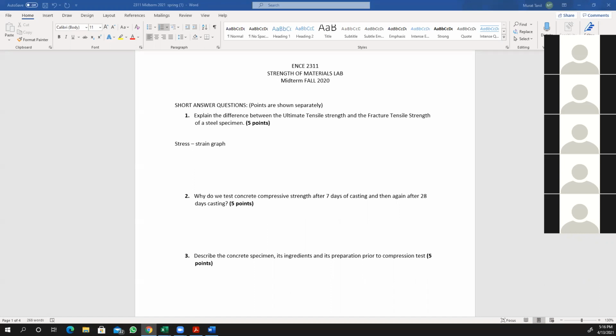Let's say you are working on highway construction. There is a bridge that is damaged, and you are going to pour concrete, and your job is to open the traffic overnight, because at nighttime the traffic is low, and the daytime traffic is much more heavy. If you see that type of problem, what you do is order the concrete with specific admixtures added into it. That gives you the 28-day strength overnight or in 2 days. There is no spec. It depends on the mixture. I can't give you exact numbers, but I can pull up Google right now, and it will tell you how long it will take for specific admixtures to get the 28-day strength.